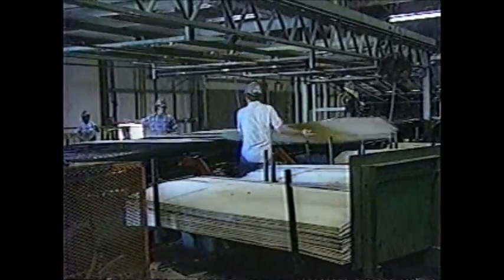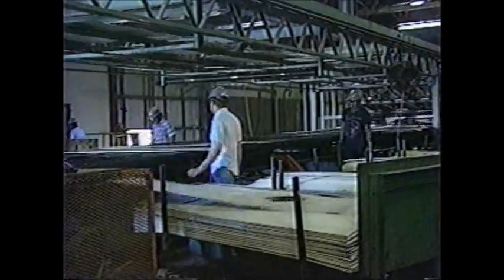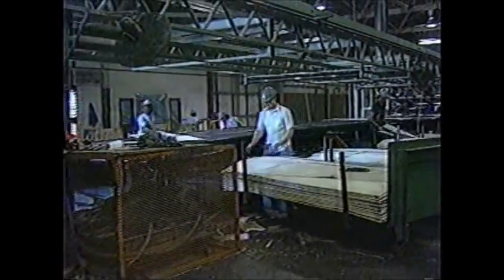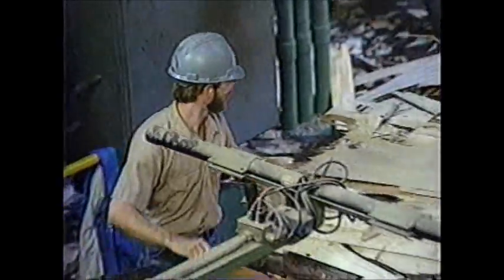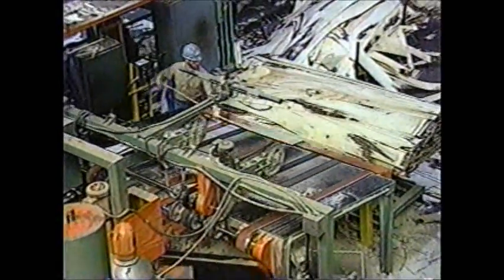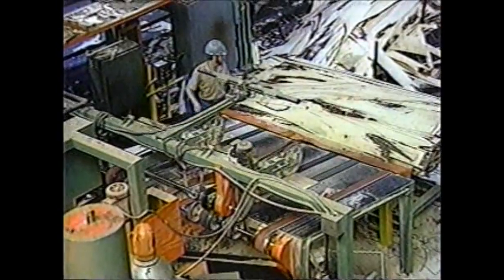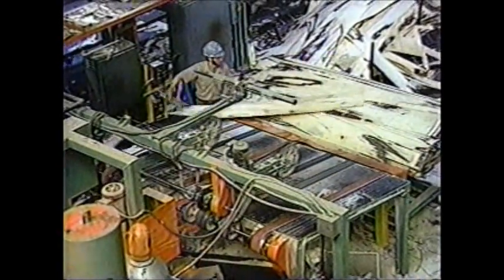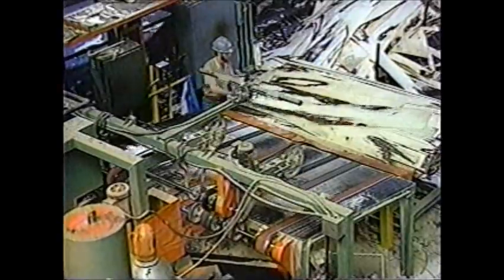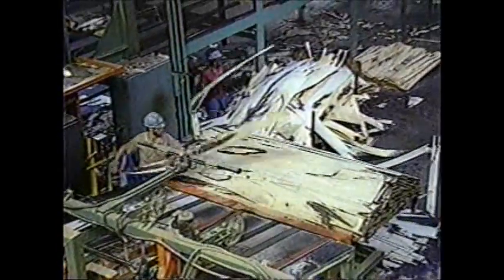Random width narrow pieces and pieces requiring further hand trimming are pulled from the conveyor into bins to be used in the inner plies in the panels. Fishtails or roundup veneer are sorted and hand trimmed to obtain as much usable veneer from each log as possible. The smaller pieces are used in the inner plies of plywood panels, termed crossbands.